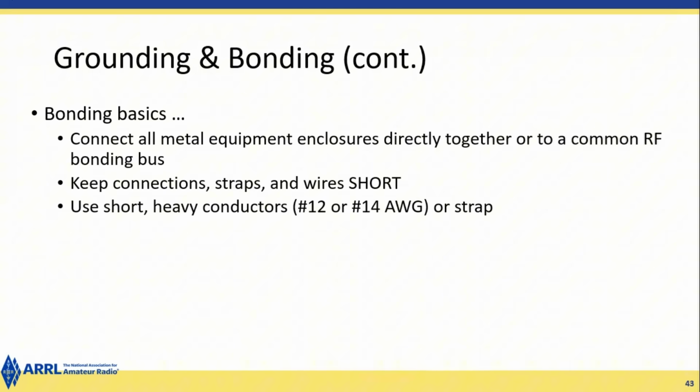C. Which of the following may cause receive interference in a radio installed in a vehicle? Battery charging system, fuel delivery system, controller, the computers, all those things. How does a ferrite bead or core reduce common mode RF current on the shield of a coax cable? Common mode A, creating an impedance in the current's path. Which intermodulation products are closest to the original signal frequencies? It's the odd order ones, the C, yes.